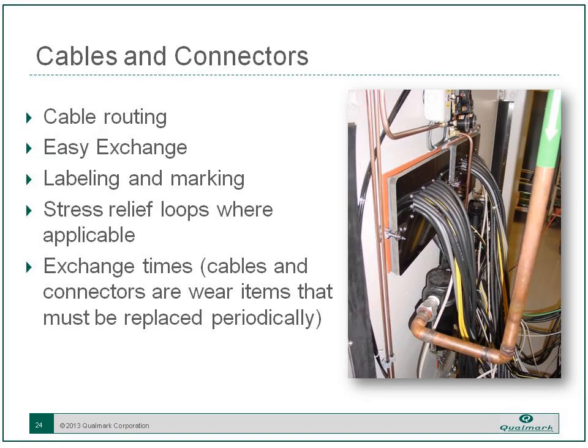Another key factor to concern yourself with is cable routing. You will have lots of cables coming out and going to your test fixture, and it's not unusual in a HASS situation to be customizing outlet ports. You'll see here one that we've had customers drill several holes in, with matching holes in the padding, the foam that's in behind that plug, so you can route the cables out neatly, and those stay permanently in the chamber, and the units inside then plug and unplug into those.